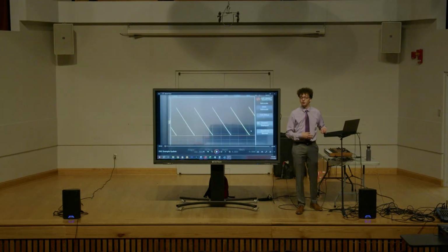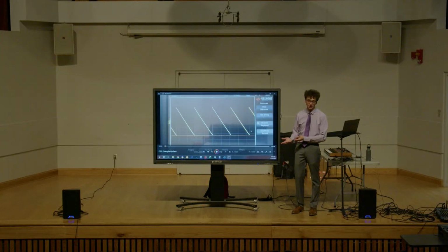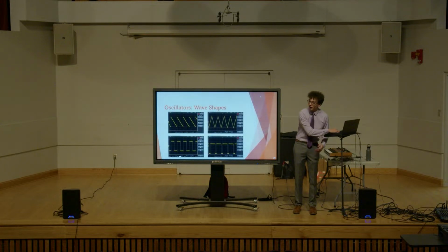So what you just heard there in order were its coarse tune feature, its fine tune feature, and then its solid triangle wave mixing feature, and then that sum being mixed with a square wave, which then had pulse width implemented on it. And every parameter that was just shown to you had a voltage control, so I could program it to be what it just was.